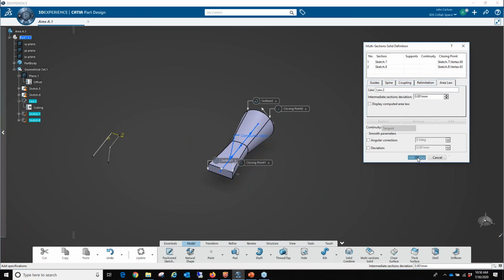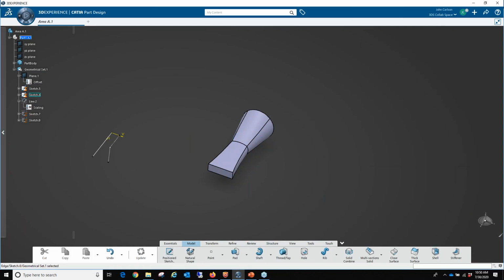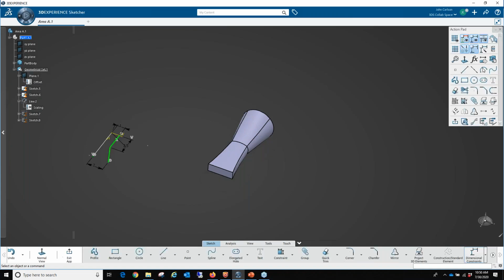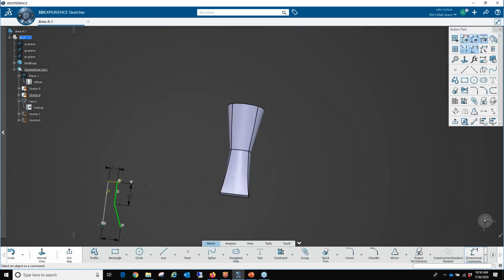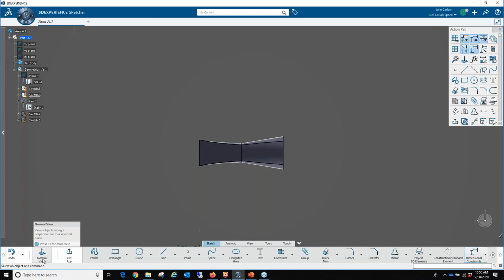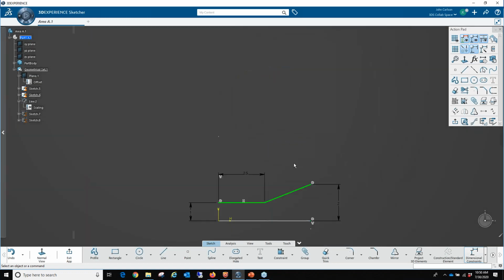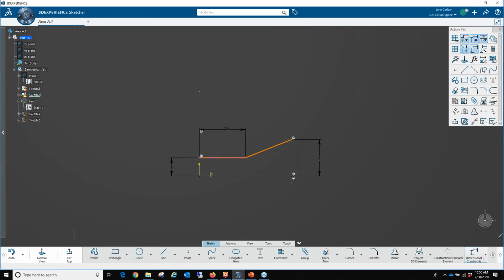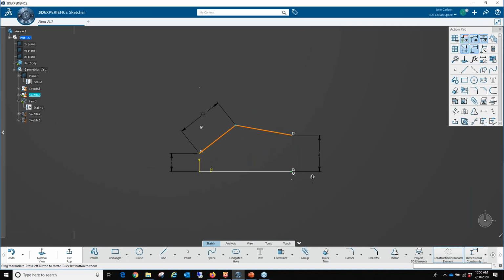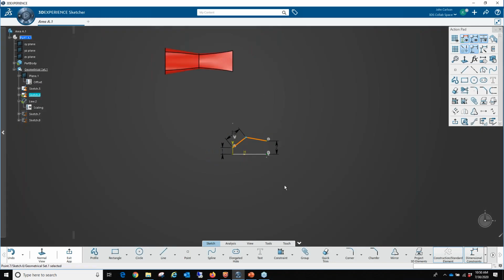So again, if I want to make some type of change, say it's not exactly what I want, maybe I go back to this one curve right here and get myself turned around the way it was originally created. Maybe I decide I don't want this area to be constant for the first 50%. So I'm going to get rid of this horizontal constraint, delete that, and drag this thing up here. Now my area is going to get really large quickly. I can't go like that, that'll be too crazy. And that's going to come back down.